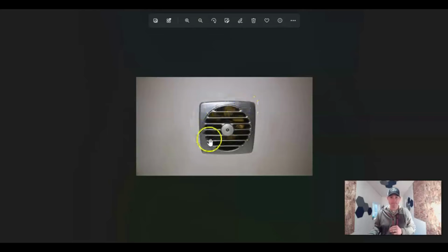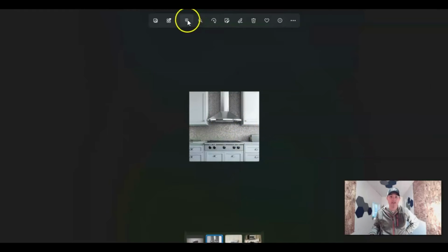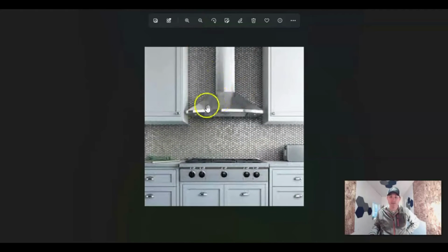But anyways, here's just the standard fan. So if you had a hood fan and it recirculated and circled back up behind you, maybe up above you, you could have a fan up there and it could then take it out that way. Let's see here. This would be a quick little picture of a decorative hood, and then the duct goes right up and probably goes out through the roof. That particular duct behind there is probably a 6-inch duct. I don't know for sure. And there's probably a damper that comes with it, and it probably sits right here. Again, it just depends on the appliance that you buy. Just keep in mind that you put that damper in to meet the requirement.